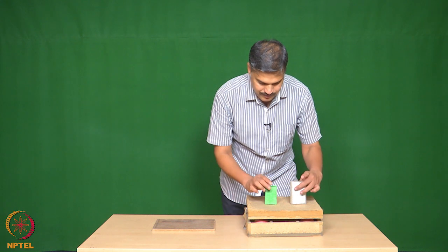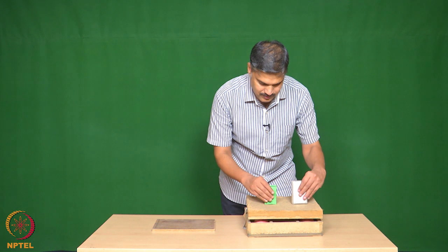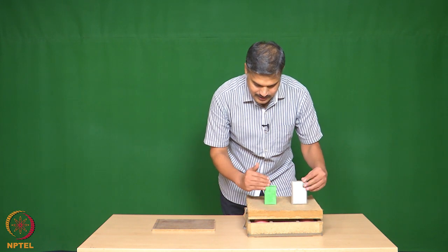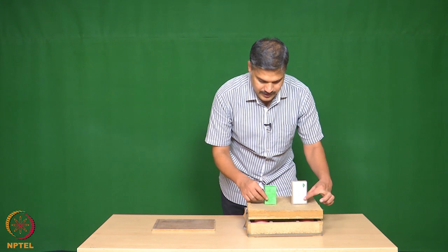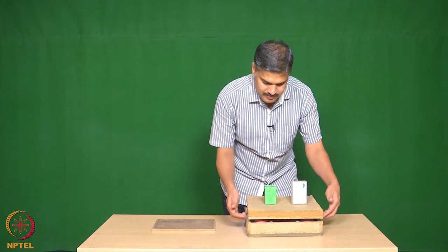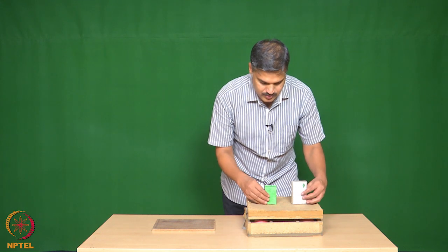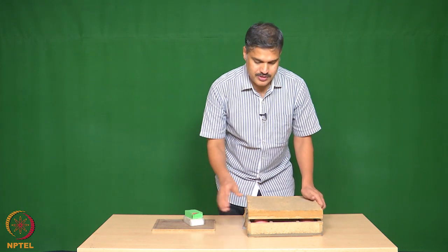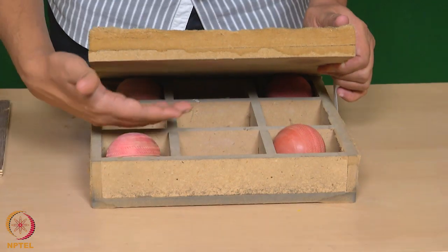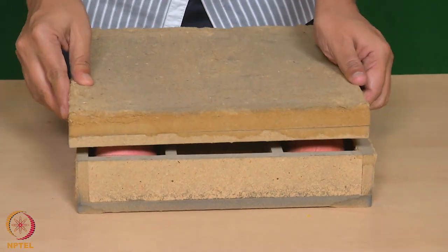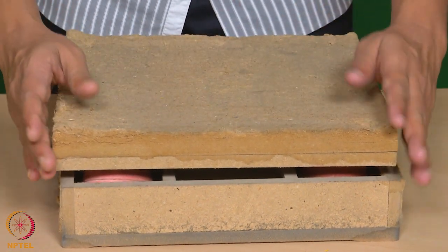So we have to understand, or evaluate, the natural frequencies of the building, and then design the bearings in such a manner that those frequencies are eliminated from the ground motion which is entering into the building. So this is called the base isolation technique. We are isolating the frequencies which will harm the structure. Those frequencies will not enter the structure, and that technique is called base isolation.